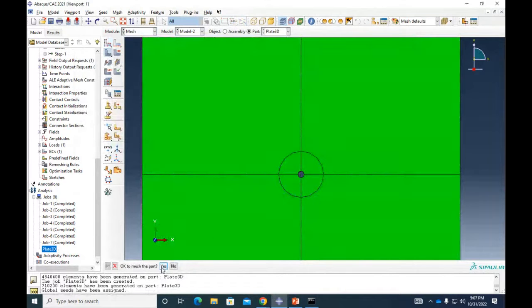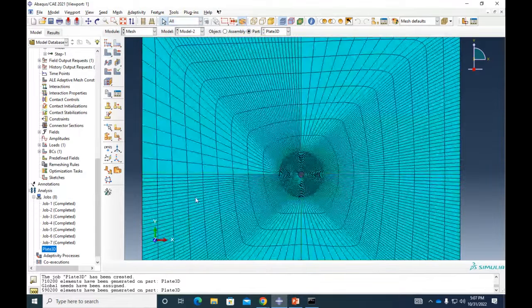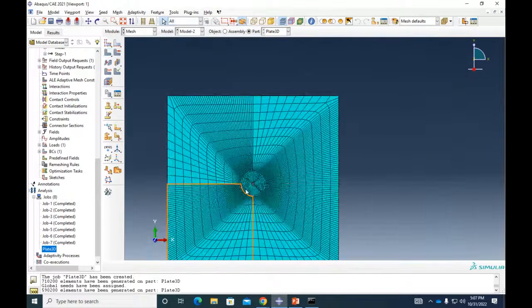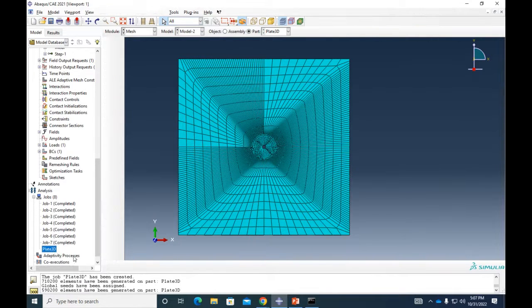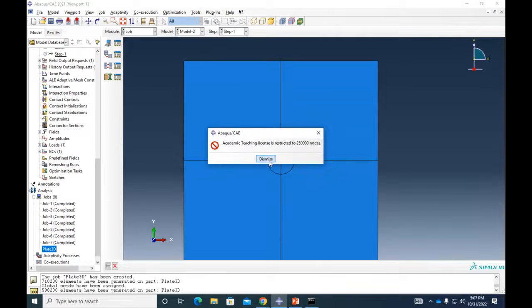All right. Let's mesh this again. But you just saw how the number of elements increases in 3D from 2,000 to 100,000, and it's the same problem. So it's good to use 2D. If you can simplify your problem to 2D, go ahead and do it, even if it's just for a basic understanding of what's going on.